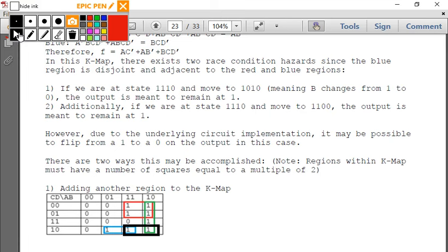I'll give you a hint. Your regions have to be multiples of 2. And what's the other thing, who was just asking me about that, they wrap around, right? So if they wrap around, what could I do? Who said that? Correct. Bottom and top. So what we would do is you would just go like this. And that's one region. So now we've overlapped blue, we've overlapped green, and we have one region.